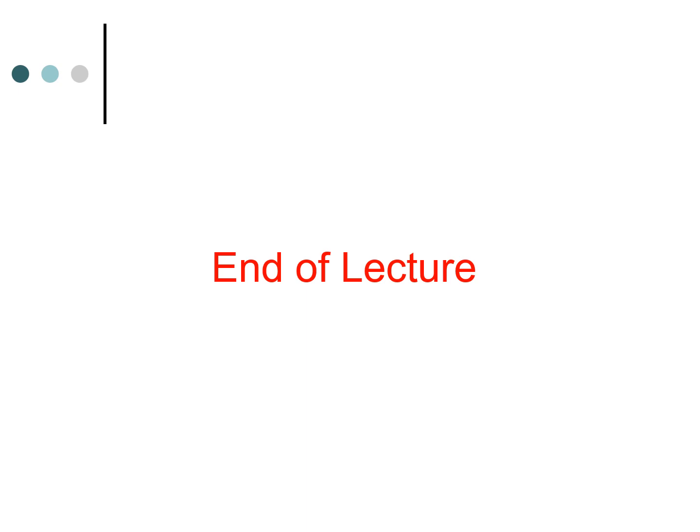So that was today's lecture, where I introduced to you the concept of viscous flow and the very important concept of the boundary layer, and how the boundary layer is essentially the way we can figure out what the skin friction drag is, what the shear stress is, and so on, and also the very important concepts of the laminar and turbulent boundary layer.